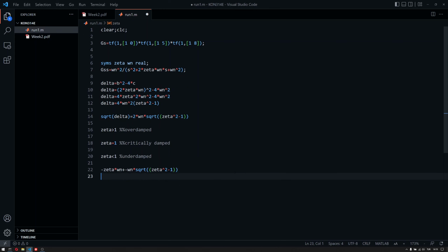Now omega n is called the natural frequency, zeta is the damping ratio, because we can determine based on zeta if it's overdamped, underdamped, critically damped. And omega n is just the frequency, and the reason for that lies in the solution. You should take the inverse Laplace transform. It has the whole time domain representation, and you can see that zeta omega n will be there, and omega n will be the frequency of the sine that will be the solution. So you can look at the textbooks for more detail. I'm going to skip this part because this is basically just a reminder for you.